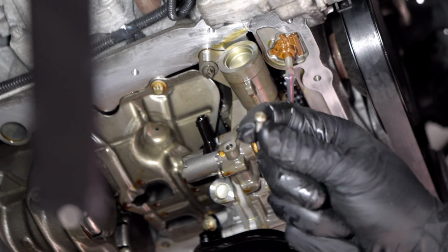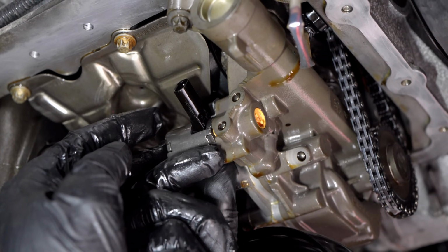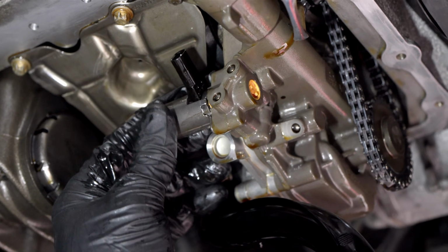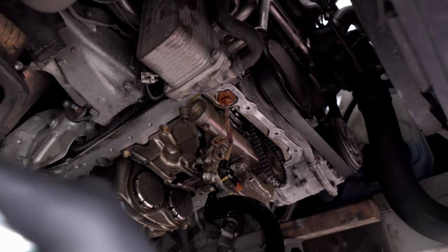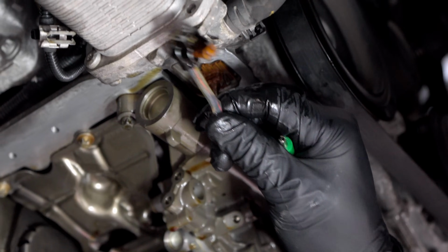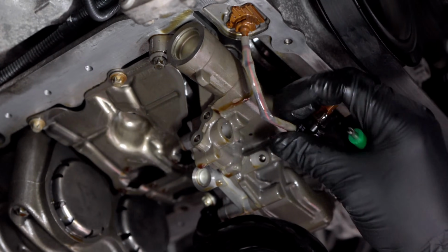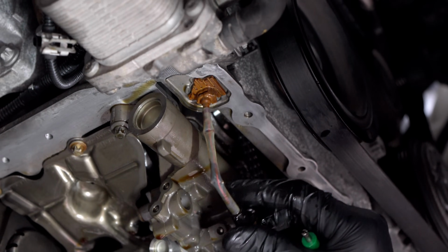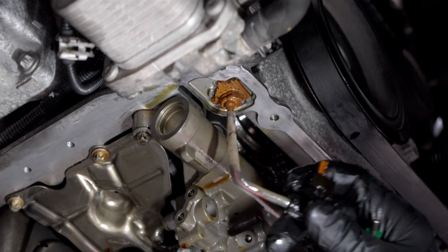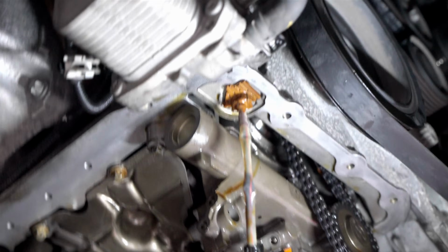So here comes the first screw. So here comes the solenoid. We're gonna slide it out, just like that. Look at it. Nice. So this wiring harness needs to be changed. So this is usually what causes the open circuit, because this wire actually lives in the engine oil constantly. So over time, this wire gets brittle and then it gives up.